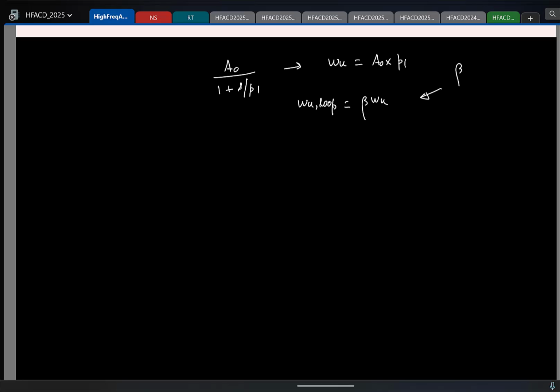Yeah, as we saw, a first order system or a single stage OTA has a very large output resistance to get a large gain. So the moment you put a small resistive load, the gain goes for a toss. So that's why we decided to have a two-stage or multi-stage structure. And we started with the two-stage.